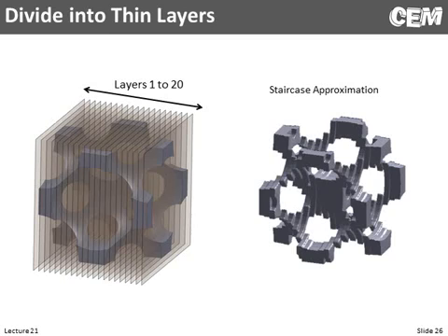So how do we determine how many layers? We look for convergence. Maybe we set a parameter up top that controls that. In this case, it's 20 layers. We'd set that parameter to 20. Then we'd set it to 10. Does our answer change much? If not, maybe we can get away with 10. But you do another convergence study with the number of layers that you're dividing up to resolve your curves.